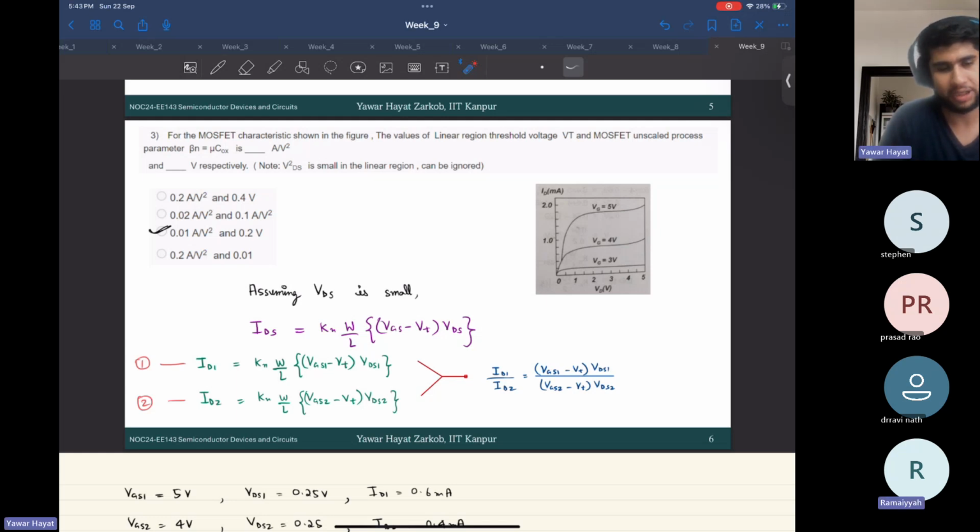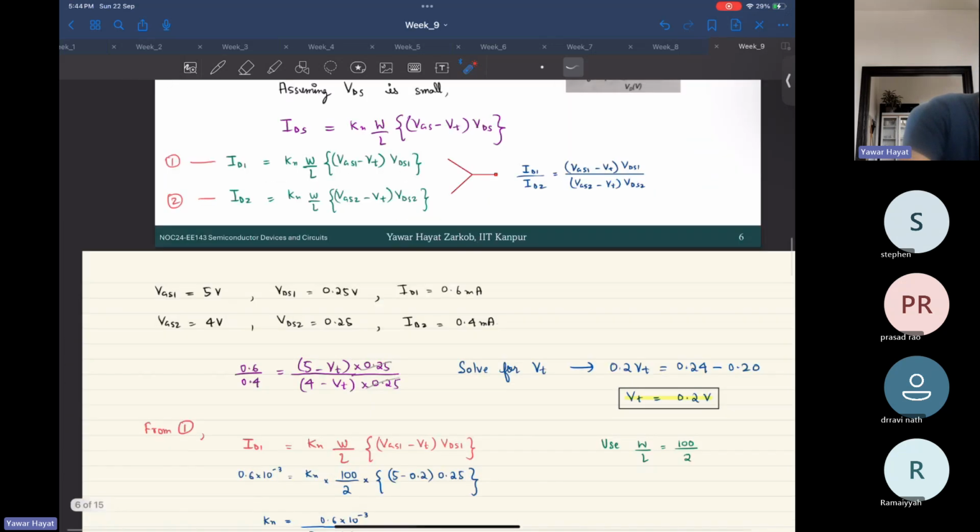Okay, sir. So that means before saturation is reached, that particular VGS value should be taken. Yeah, before saturation is reached. And before the saturation is reached for both the VGS values, right? For this one as well as this one, right? Because for this one, the saturation would reach earlier, at VGS minus VTH. I hope that's clear. Clear, sir. Okay, fine. Thank you.